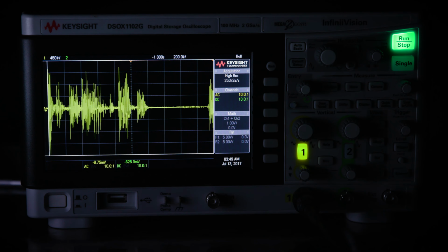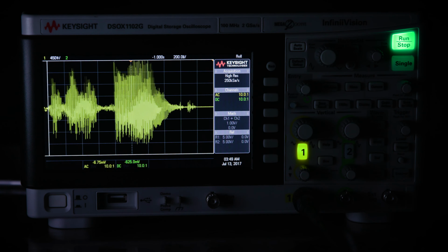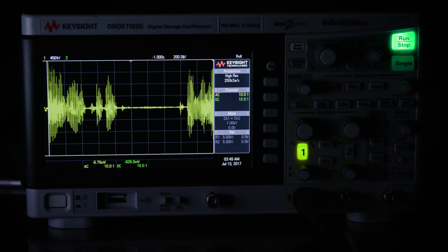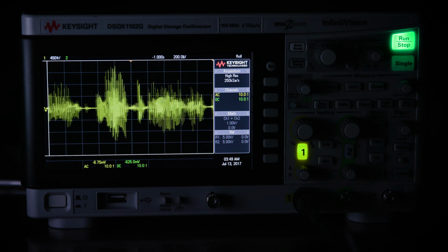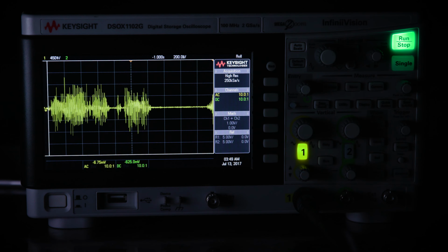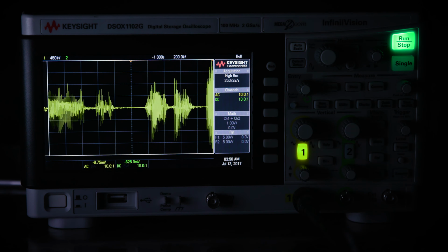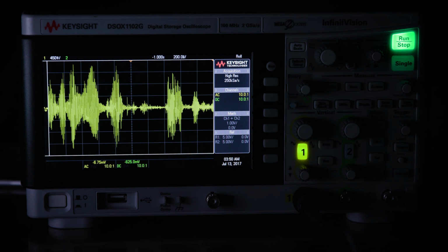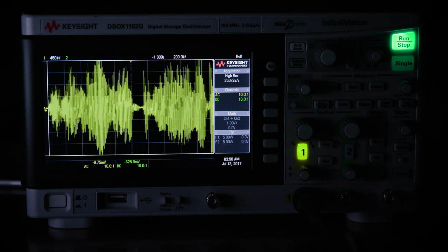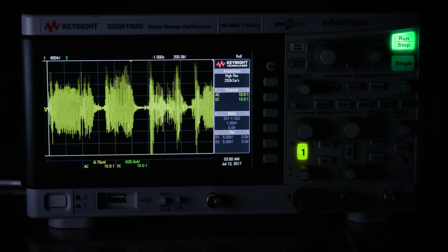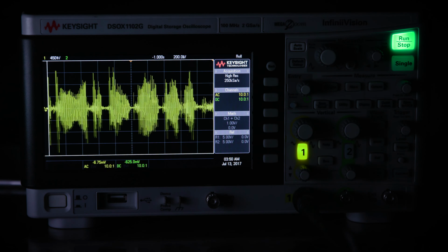I know we've seen another test and measurement equipment vendor doing triple interleaving instead of double interleaving, and we see that pretty clearly in the noise floor. There are many ways to interleave AD converters. The devil's in the details, and it's really what kind of SNR and SFDR you can accomplish.